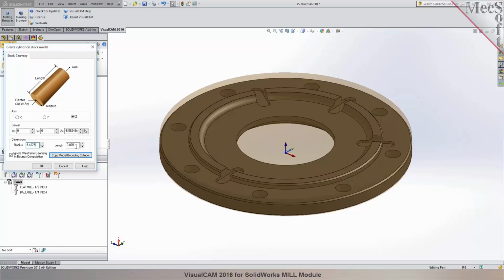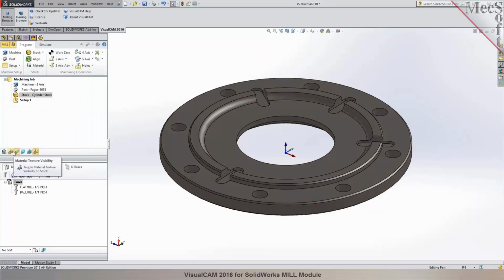I mean the stock, the bar stock, they have round numbers, so I guess the radius would be 5.5. So 11 inches, no? Yeah. Yep, radius is 5.5, which is diameter is 11 inches. And how about the length? The length, I cannot read the number, it's too small there, but it's 0.875, the length. Well, we would make it, I think they have a minimum of, what is it, 1 inch or 1 1/8 for the cut. Okay, so let's put it at 1 inch. 1 inch? Okay, great. So I'm going to define the stock to be 1 inch.